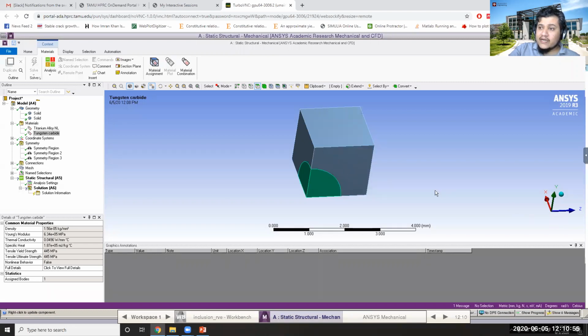It doesn't do anything special, it is just another displacement boundary condition, which will enforce the condition that the displacement in the x-axis, the axis perpendicular to this face, is going to be 0, as well as the rotation about the z and y axes. So these three things will be enforced as 0.